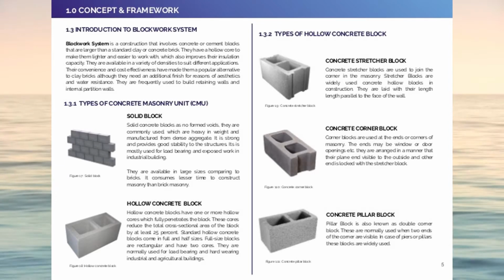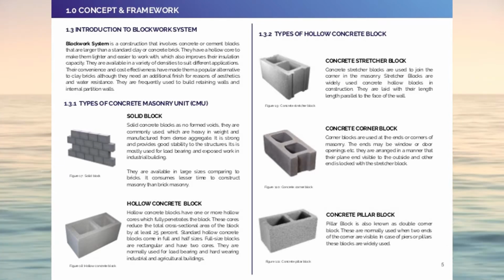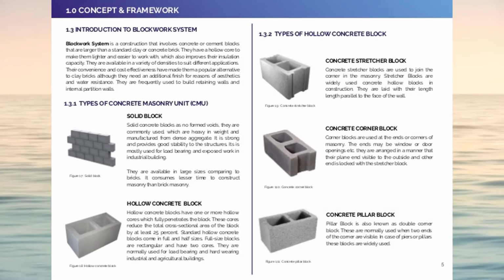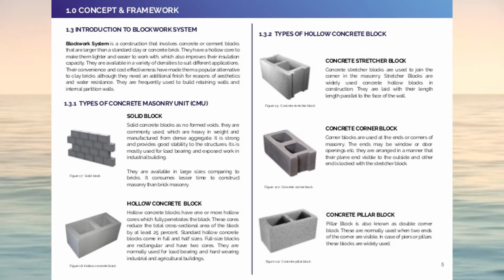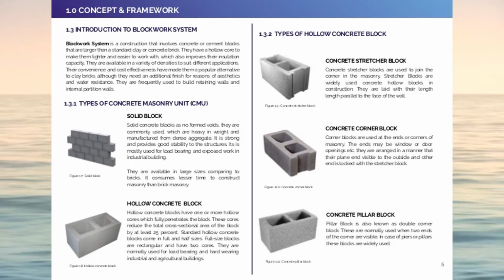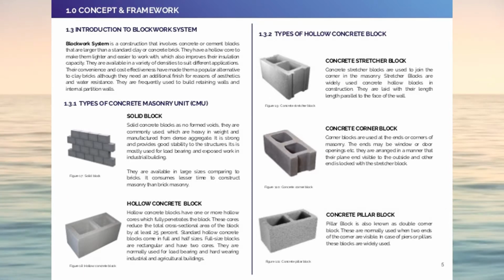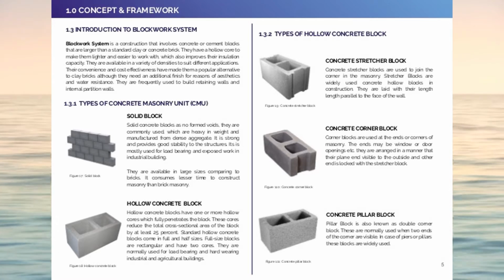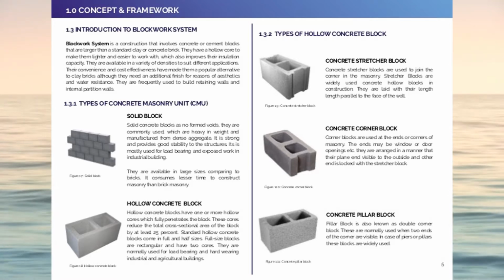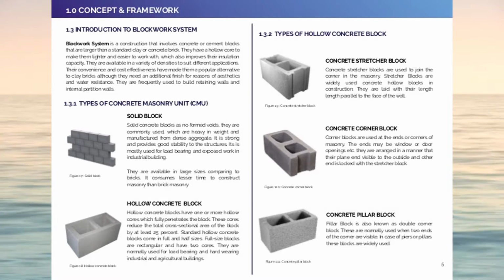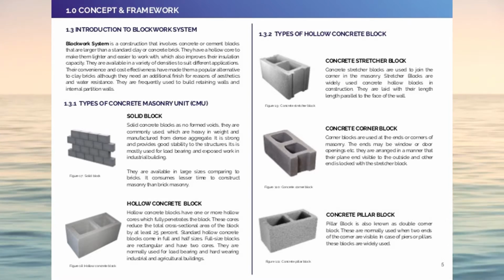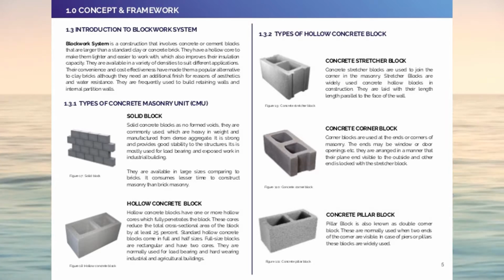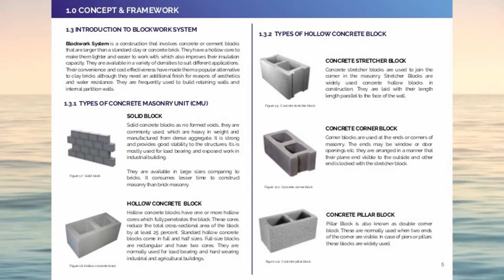Solid blocks are commonly used, which are heavy in weight and manufactured from dense aggregate. They are very strong and provide good stability to the structure. So, for large work of masonry, like for load-bearing walls, these solid blocks are preferable. They are available in large sizes compared to bricks, so it takes less time to construct concrete masonry than brick masonry.